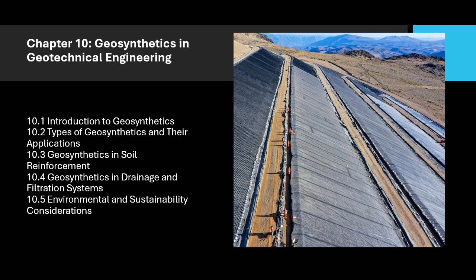In road construction, geogrids help in distributing the load more evenly, reducing pavement distress and extending the life of the roadway. 4. Base course reinforcement. Geogrids are used to reinforce the base course of roads, railways, and other paved areas, improving the overall performance of the pavement structure.